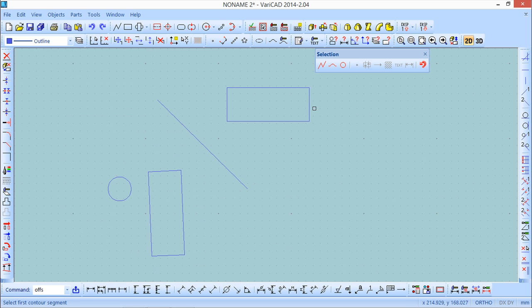So okay, first contour is this guy. I want to use this direction, and the side that the contour will follow is outside. So next click with the left, next click with the left, and I'm okay. Just these 3. Now I will press enter with my right mouse button. Okay, the offset side will be out again, and that's it. Okay, very, very nice.